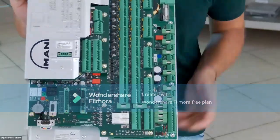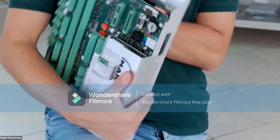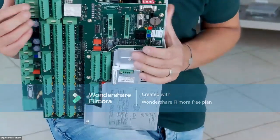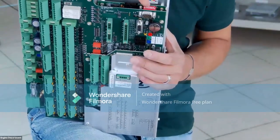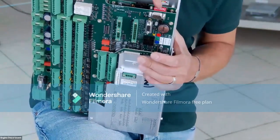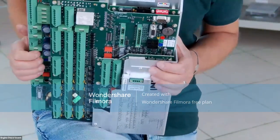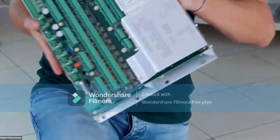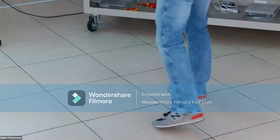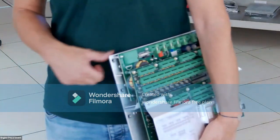How you perform the force download? You are accessing the side dip switch, color dip switch, and you switch the position of number 4, the dip switch yellow number 4, from on to off. Okay, so before installation, you change the position of number 4 from on to off. Okay, and now you are installing the MPC on place. So on our simulator, we install the same MPC on scavenge control unit controller, and will perform a force download.